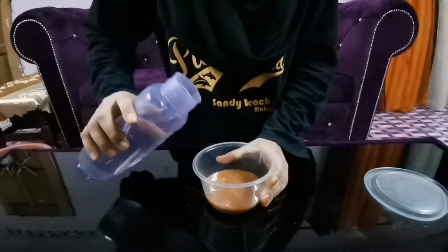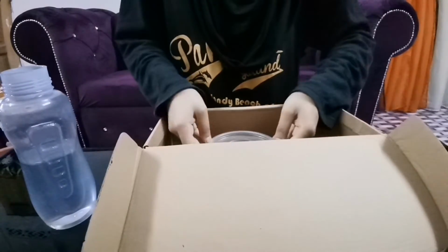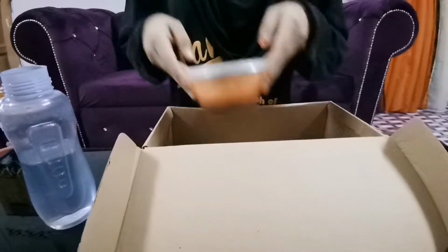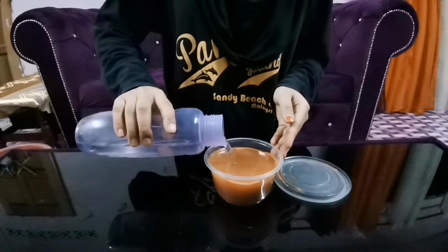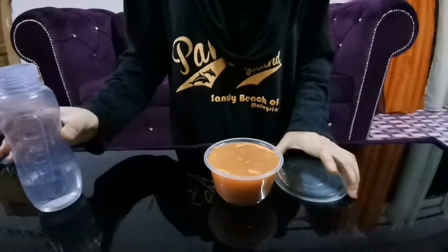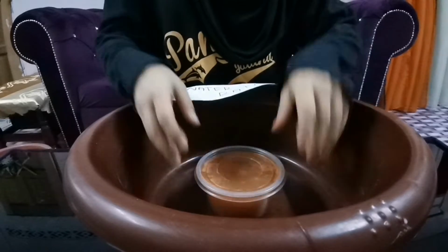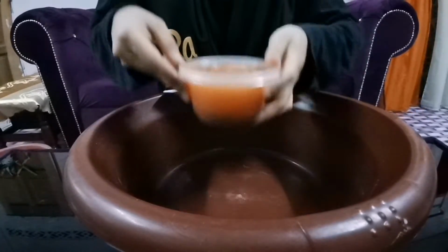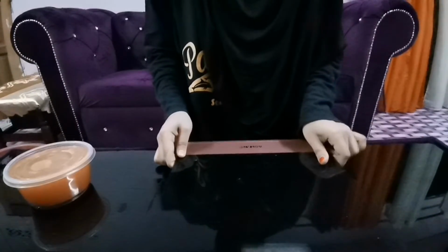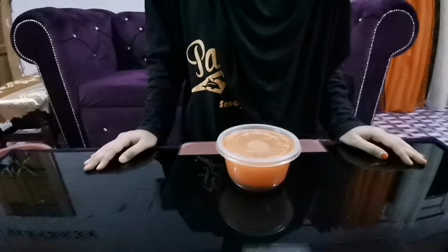Pour some more water to make the plastic bowl half full. Remove the entrapped air by applying partial vacuum. Next, pour some more water into the plastic bowl and fill it completely without any entrapped bubble and put the stopper on. Keep the plastic bowl on the basin that acts as water bath for 1 hour. Take out the plastic bowl from the water bath and wipe it clean and dry from outside. Weigh the plastic bowl filled with water and soil sample with stopper. Record the mass as M3.